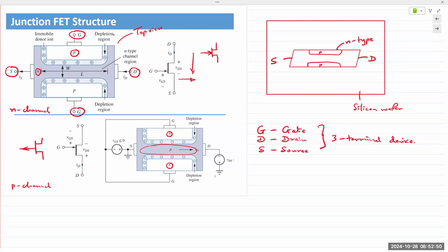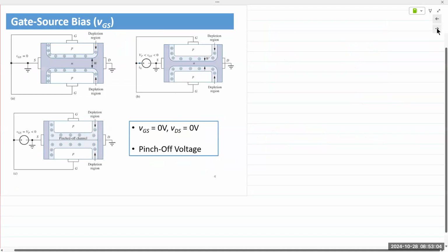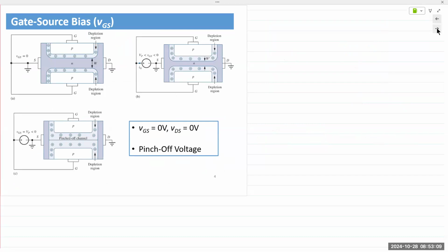Good so far? Question? Lots of questions. It is. That's what it is. That's what all transistors are. That's a switch. Okay, going on a bit of a tangent. Transistors, FETs, they have two primary modes of operation. On, off, so it's a switch, and there's a linear region where you use it as an amplifier. That's it. All digital logic circuits are just switches, right? Zeros and ones. Was that any sort of revelation?